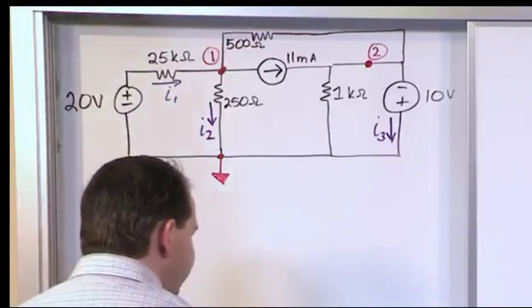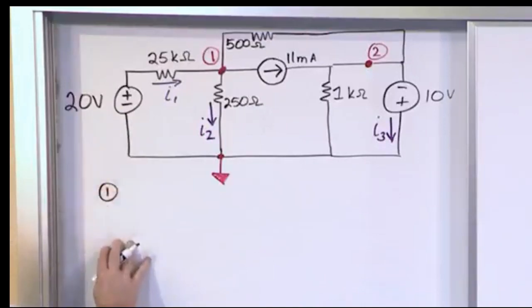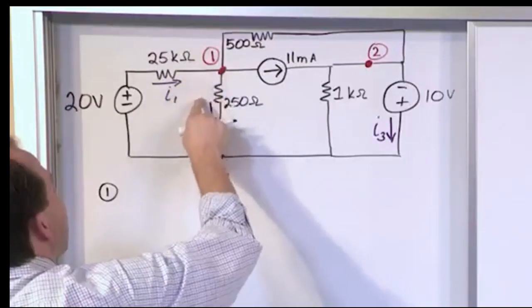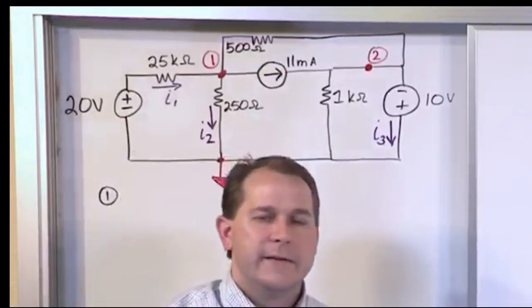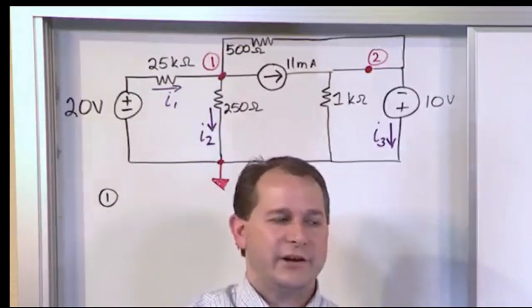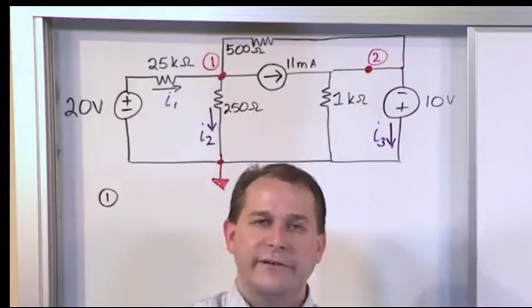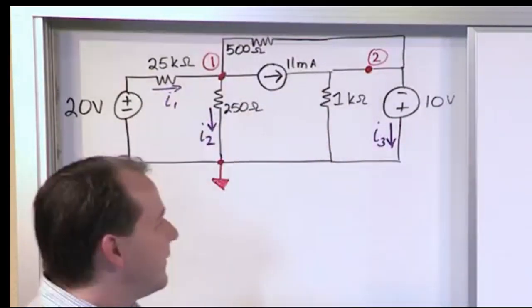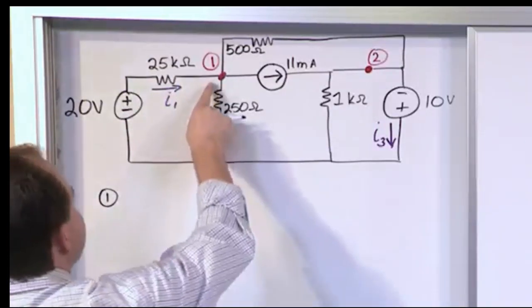All right, so let's proceed just like we would typically. Over here at essential node 1, what would be the node voltage equation? So we're looking at the current going out, out, out, and out. For now, you completely ignore what is drawn in the picture. The picture is what I'm trying to supply as an answer, right? But the node voltage method requires that you write your equations as if the current is leaving the node. So write them that way. Get the answers, and then later on when you're trying to tell the teacher what these currents are, you'll reconcile it with what's on the paper. Because half of these currents might be drawn backwards on purpose just to confuse you. And they probably are.